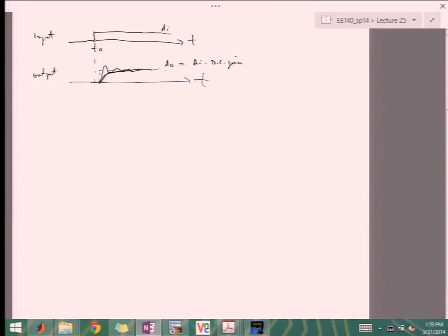Okay, and by tuning pole 1 to pole 2, and in fact this will depend also on your phase margin, you'll have a different scenario here, a different amount of peaking where you want it. But this is all small signal stuff, right?